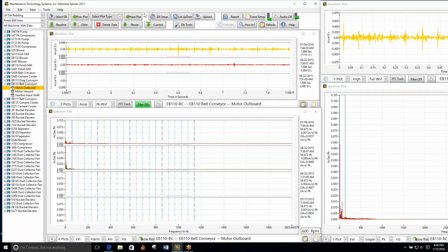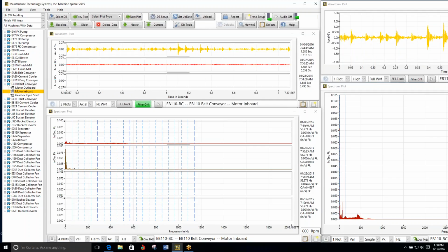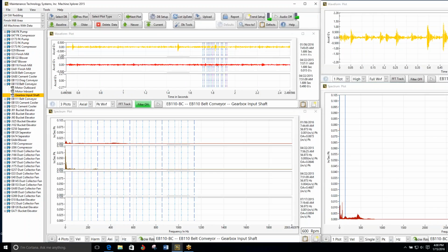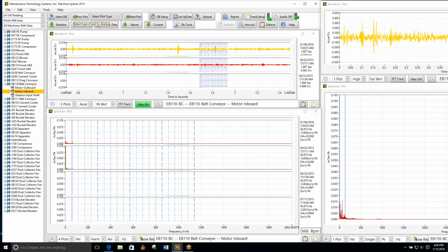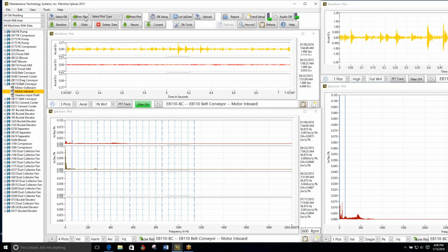Okay. There's got a little bit of hit going on, some pattern, but the amplitude is low. That's a little higher. Certainly changed since April. And I would guess that this has the potential to be caused by a coupling, would be my guess.